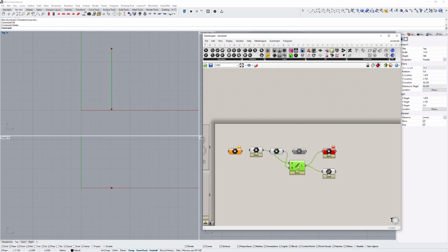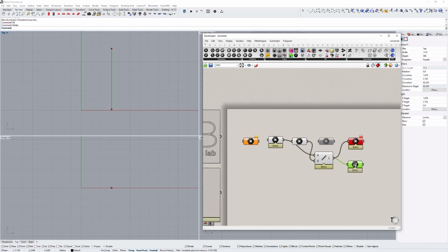That's more or less previewing the script, or at least understanding what the colors of the components mean and what they represent. Up in the top right, we have 2 main options. One, on the left side of this vertical bar, is draw shaded preview geometry, which means anything that's light grey will show on the desktop in Rhino's viewport. And if I click the green and grey button, it allows you to only preview geometry that you click on.